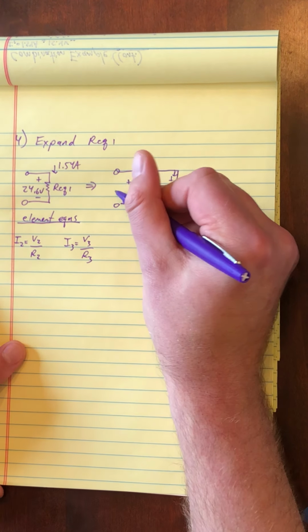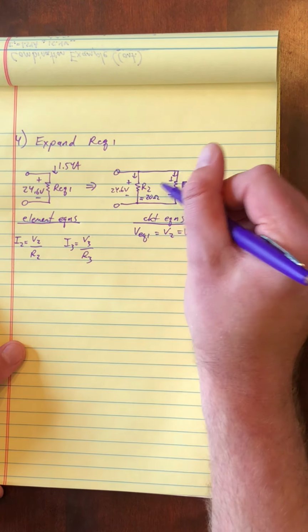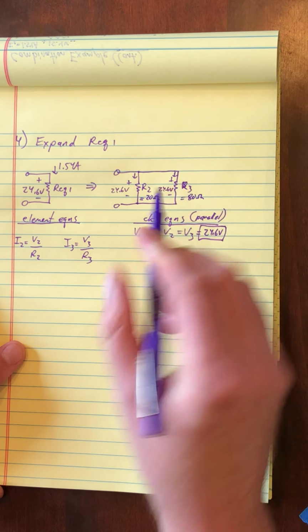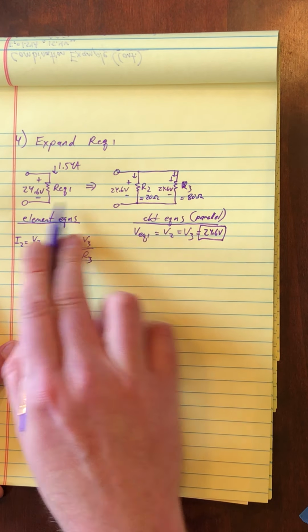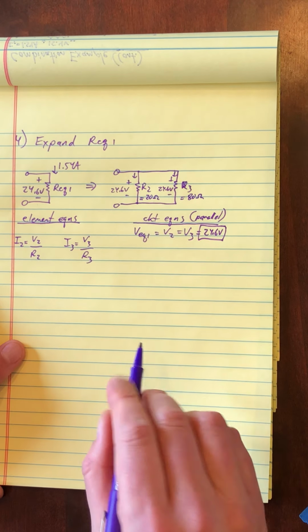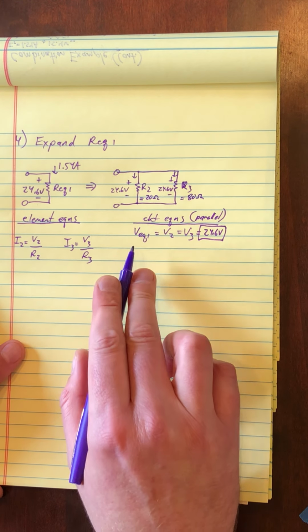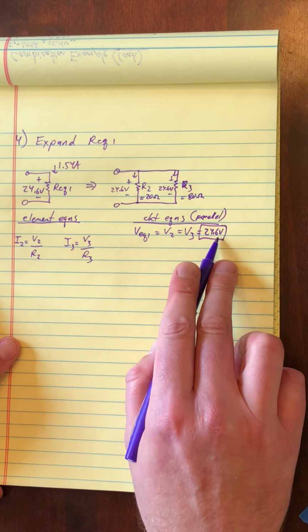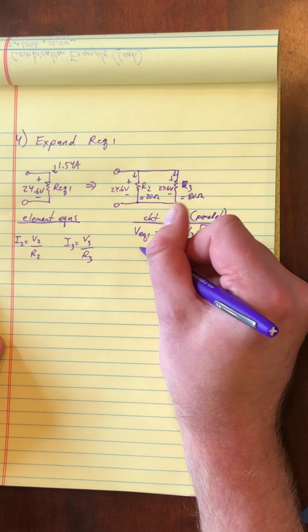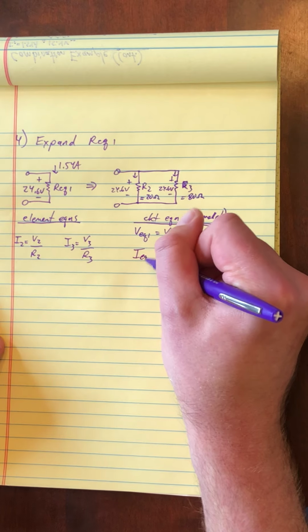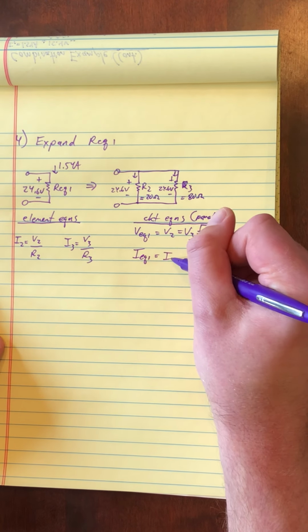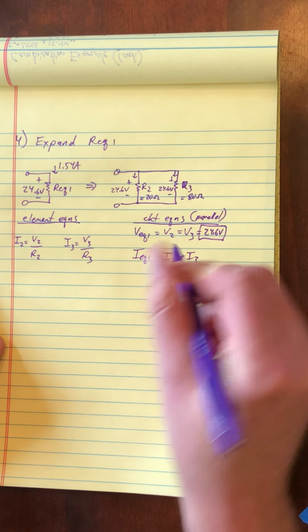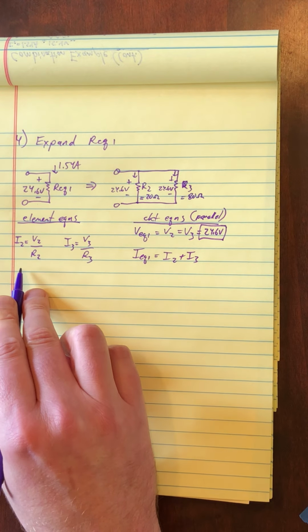So great, I already have these values, 24.6 volts. And in parallel, the voltages are the same, so that's what we took over and showed that. And so how do I get the currents? So this time I have the currents directly here in the element equations. All I needed was this voltage, so we don't even need to use that IEQ1 is equal to I2 plus I3. It's going to be redundant. I can use it as a check.